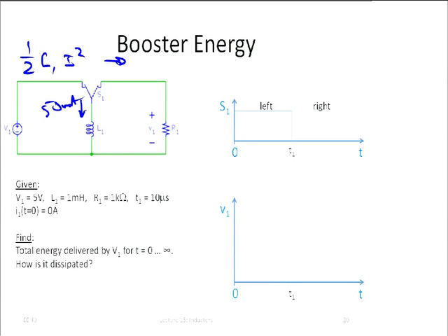You could do the same thing also with capacitors, but if you want to make it with high efficiency, you need a current source to take your energy from, because otherwise you always charge the capacitor from a constant voltage, and initially the voltage across the capacitor is 0, so you're dissipating half of the energy, as you point out, in the wiring resistance or switch or whatnot. Okay? So that's a good point.